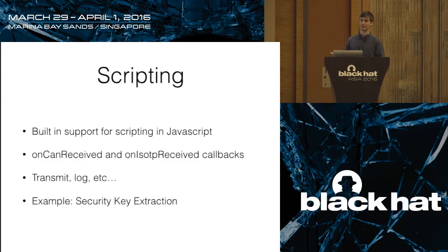So I wrote a simple script that pretended to be a car. And whenever it received a request to send a seed, it would just start at 0 and send the next consecutive value. So you get the seed of 0, 1, 2, 3, 4, 5, 6, 7. Keep going, and then whenever you got a response, it would print out what the valid key value is. I did this for about 10 different values, and then realized that it was just arithmetic. It was 2 bytes. The first byte you added a number. The second byte you subtracted a number, and that was the entire authentication mechanism.